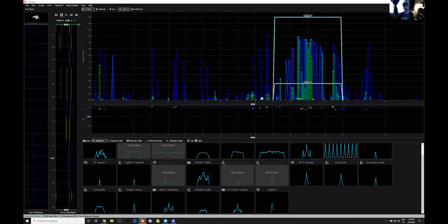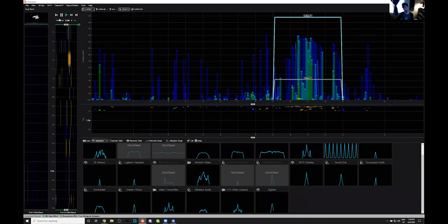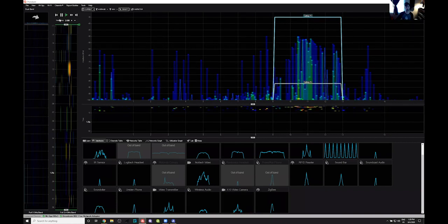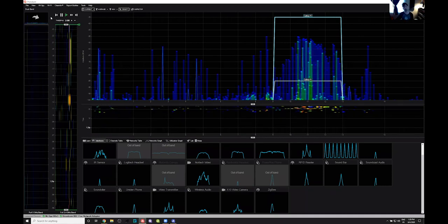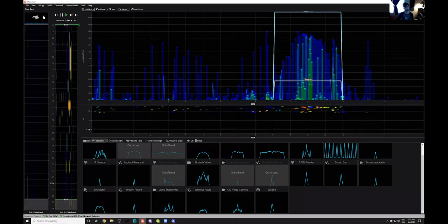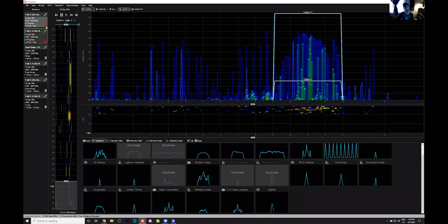And so right now we started a new session. I just removed that source of interference, and I want to bring up how sessions work in Chanalyzer. Once we went into that device finder, it focused the resources on such a small portion of the spectrum that it no longer was sweeping around it. And so to go back to those sessions, you just go to View and Session Manager.